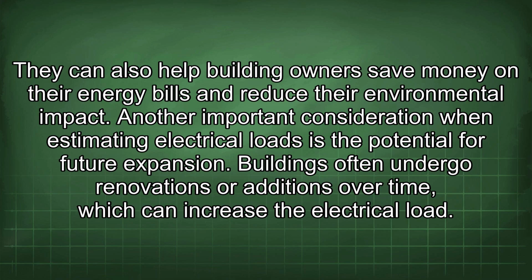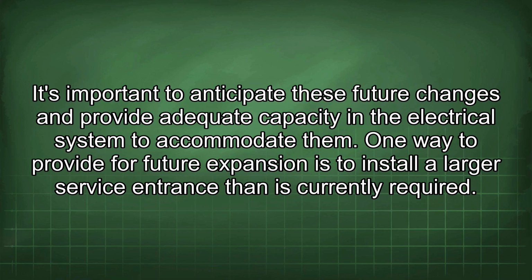Another important consideration when estimating electrical loads is the potential for future expansion. Buildings often undergo renovations or additions over time, which can increase the electrical load. It's important to anticipate these future changes and provide adequate capacity in the electrical system to accommodate them.